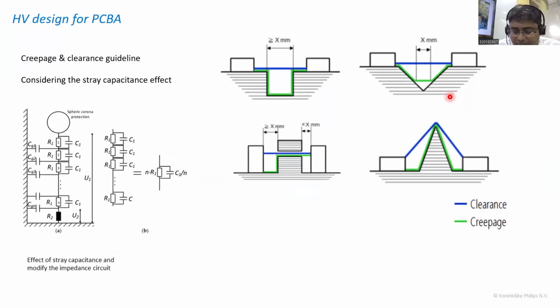And what I wanted to point out here: the X-ray generator, from an electrical point of view, is a combination of power electronics and high voltage. Power electronics boards generally operate at a maximum of 300 or 400 volts, but here they need to produce 150, 160 kilovolt at the end. Hence they are all immersed in oil, and some special care must be taken in the board, the raw PCB design. So all the high voltage concepts we use in insulator design in the power industry are equally applicable here.